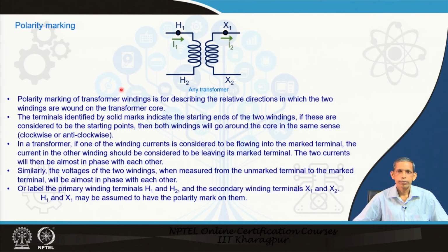One thing that we see is that for a 3 phase system, for each phase the current has to be tapped and that should be the input to the relay. So, the corresponding currents are being processed in the relay. Now, unless there is a proper polarity of the corresponding current, we cannot integrate the corresponding currents properly. Therefore, while connecting the CTs, we essentially require the corresponding polarity of the transformer.